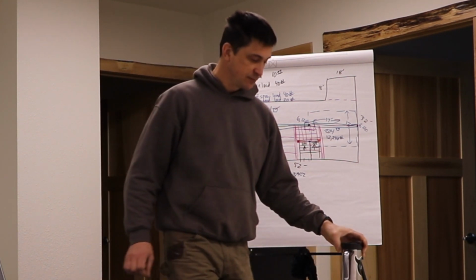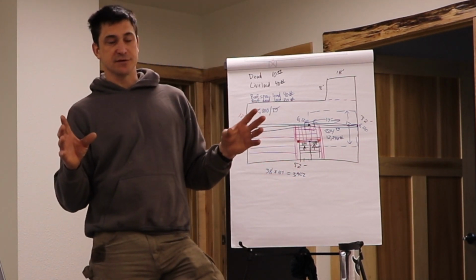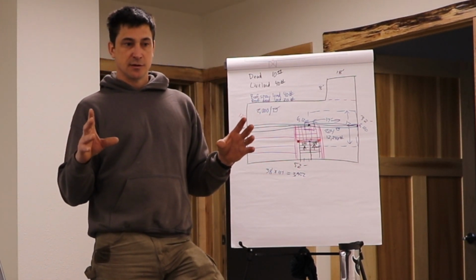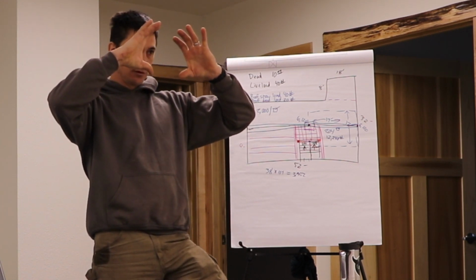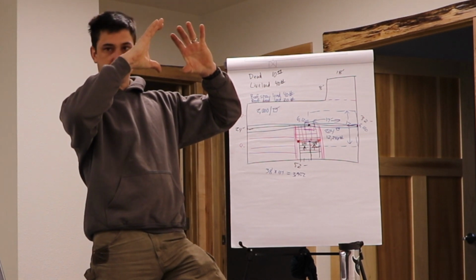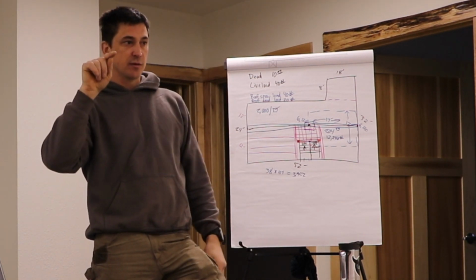Just a note for you guys, a general comparison: to move an equivalent amount of BTUs, I can do it through an 8-inch round duct with forced air, or I can do it with a 1/2-inch diameter pipe and hot water.